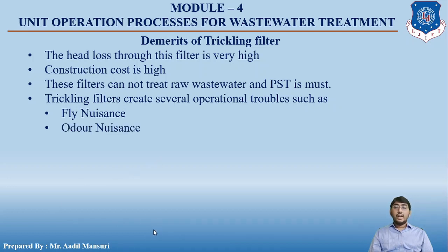Next problem is odor nuisance. Odors generally do not prevail in trickling filters where rotary distributors are provided. But if fixed nozzles are provided, then hydrogen sulfide generation creates a problem. In these circumstances, wastewater may be chlorinated.